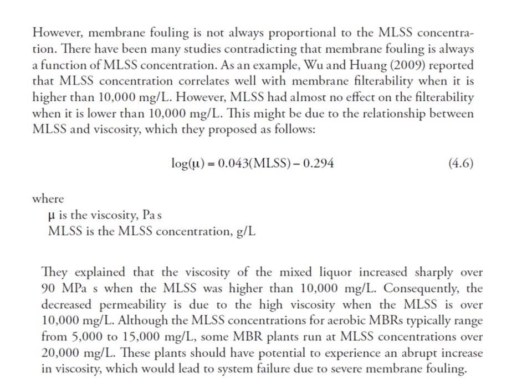As I already mentioned, membrane fouling is not always proportional to the MLSS concentration, and there are many studies to explain this contradictory result. One of the results shows that when MLSS is higher than 10,000 milligram per liter, MLSS concentration correlates well with membrane filtrability. However, MLSS had almost no effect on filtrability when it is lower than 10,000 milligram per liter.